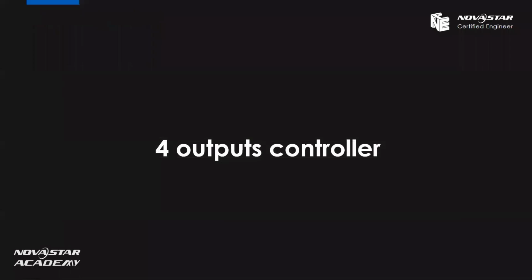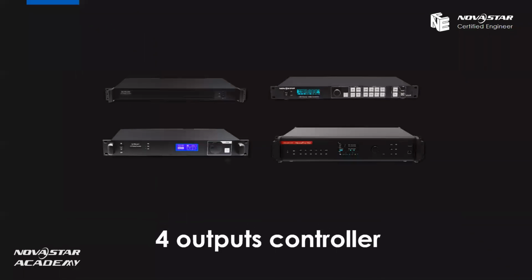Okay, another question for you. What about the 4 output controllers? As we know, for 1 output port, the loading capacity is 650,000 pixels. So what about 4? Can we use 650,000 pixels multiplied by 4? After calculating, is it 2.6 million pixels? Actually, 2.6 million pixels is not correct. 2.3 million pixels is the real capacity of the 4 output controller.